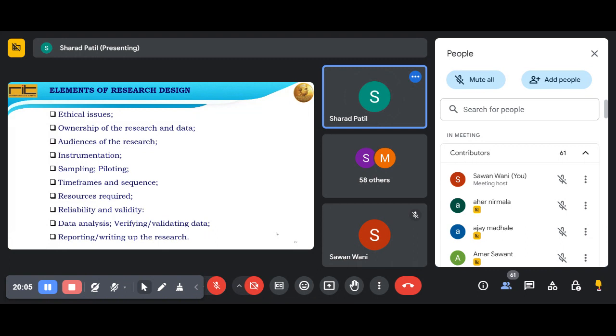That is very important. You need to check whether the data generated is as per the fundamental laws or not. Suppose we are adding some additives to improve thermal conductivity, and when you take the readings you do not find a major change in the heat transfer or the conductivity after adding them. Then definitely there is some error, or the procedure you adopted for these experiments might have some errors, because of which the data generated is not valid, or you need to verify it. That is very important.